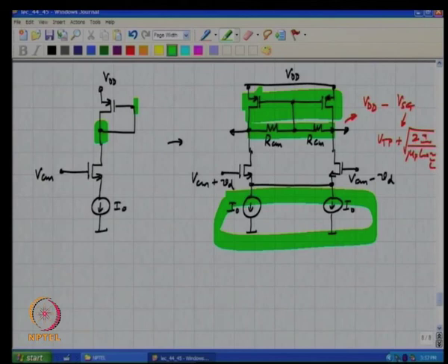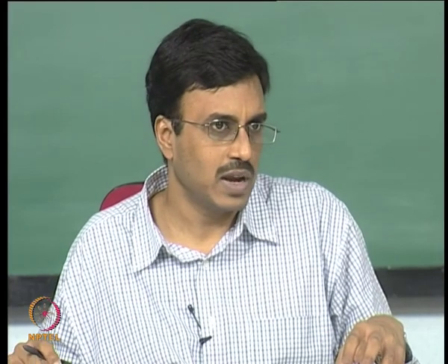In the next class, now that we have made a fully differential amplifier with some gain, we need to add all the rest of the pieces of the puzzle, right, and most critically we need to interface the latch to the preamplifier in the right manner. Please recall that the preamplifier output is only relevant at the sampling instant of the latch, right.